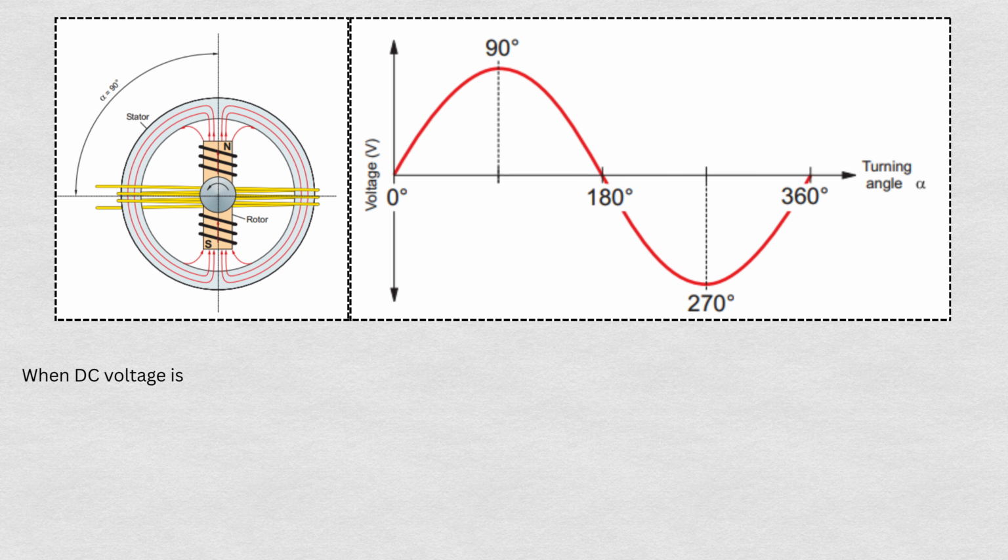Relative motion is achieved as the rotor turns inside the stator. One cycle of an alternate sine wave voltage is produced for each complete revolution of the rotor. Induced voltage in the coil increases as the rotor turns toward the coil. The induced voltage is proportional to the variation of flux which is perpendicular to the stator coil.